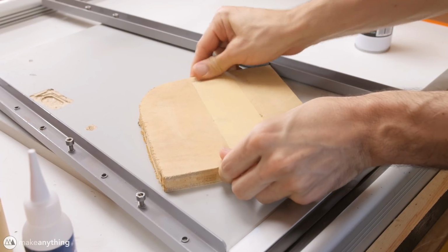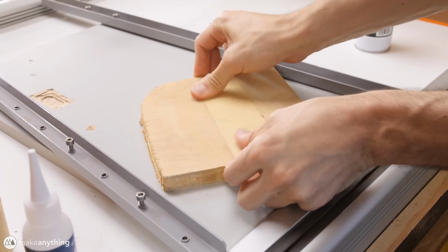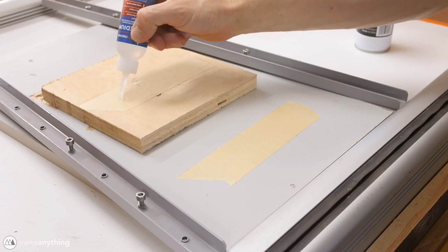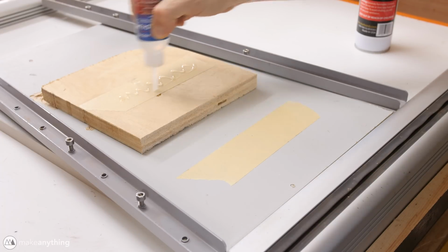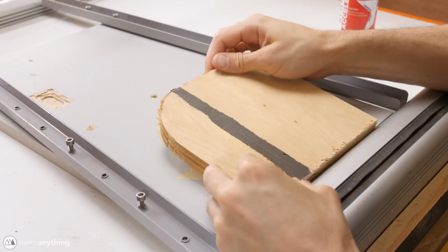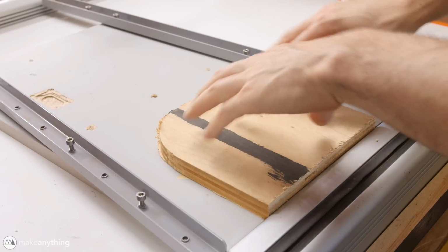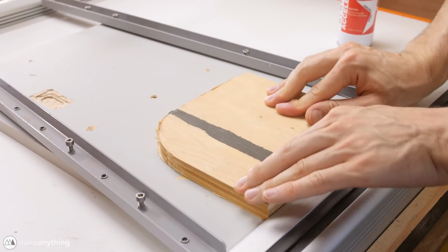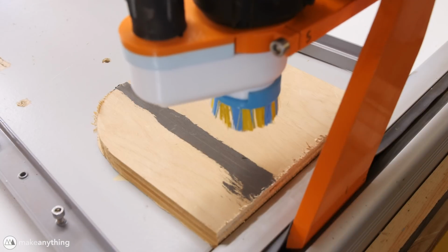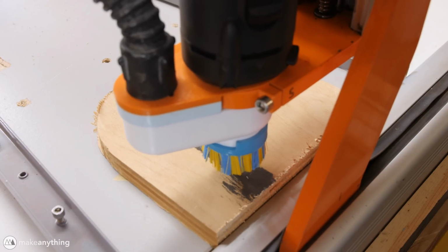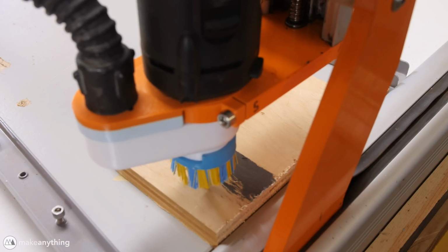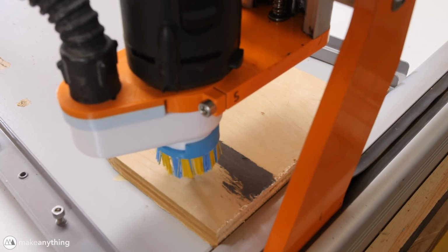To start out, I'm just gonna do a small test on plywood, just because I haven't done anything quite like this before, so I don't wanna go straight into possibly destroying my final piece. And one of the coolest tricks that you guys shared with me in the comments of my last CNC video is that instead of dealing with all these different clamps to hold my wood in place, you can just put masking tape on the piece as well as on the cutting surface and then super glue those together. I love that. It saves a lot of time and setup, and it leaves the piece completely free floating, so you don't have to worry about accidentally running into a clamp or something as you run the CNC.